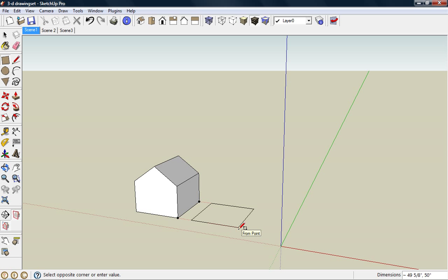Now if you look at the measurement toolbar, the first dimension there has a little squiggle or a tilde in front of it. That's telling us that this dimension is not exact. It's actually rounded off. The second number, 50, is actually set from those reference points that we're inferring off the first object that we drew.